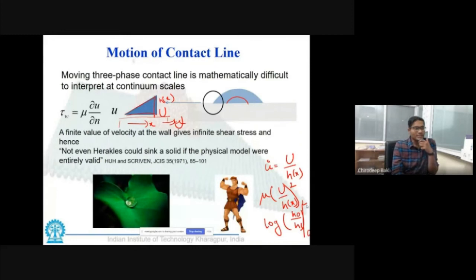Without going into the mathematics, understanding it from the physical argument, the fluid element next to the solid element is not moving, hence the contact line can never go from point 1 to point 2, because a fluid element next to a stationary surface doesn't move. So this makes the situation an impossible thing.